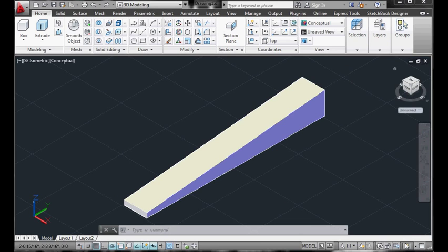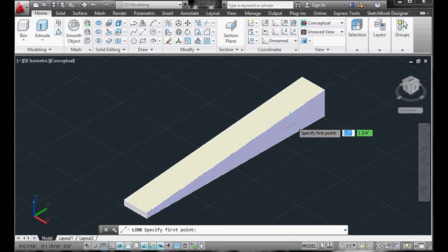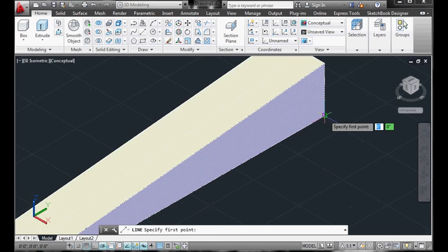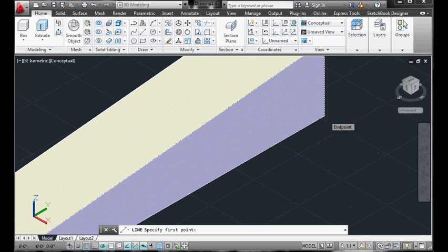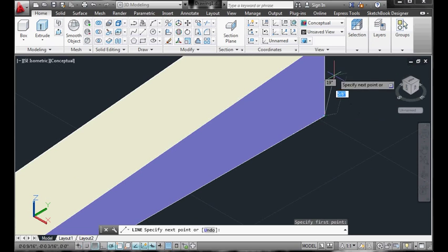So the next step we have is to locate the holes for our axles. We're going to do this by applying a line from one end to the other as a midpoint for all our axles. So first thing you're going to want to do, if you'd like, you can zoom in and click on the end point there. You notice you get yourself a line. We're going to take our line straight up 3/16 of an inch. So you're going to type in 3 divided by 16, hit enter.